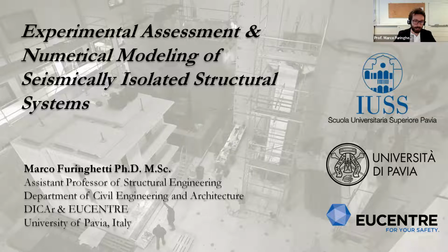So your question is actually about when we have an already flexible structure, or a soft soil, so that the soil structure interaction leads to a higher value of period. Can we use base isolation, or how can we design the bearings? I will leave the design to the lecture of Friday, where we will see all the rules for the technologies, which are rubber bearings, lead rubber bearings, and friction pendulum.